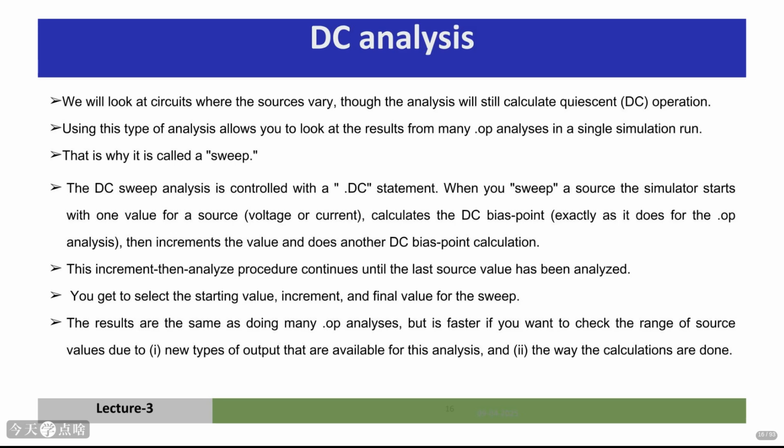Controlled by a .dc statement, it essentially runs multiple .op analyses automatically. You tell it which source to vary, the starting value, the increment, and the final value.